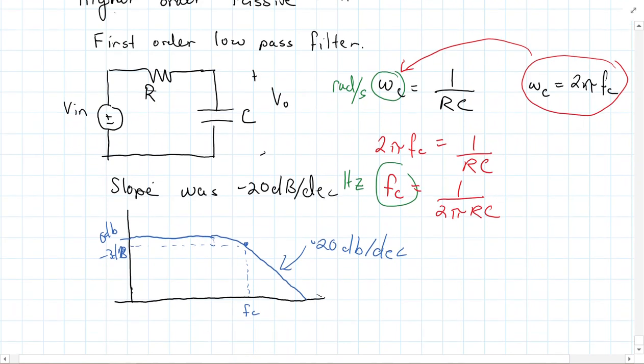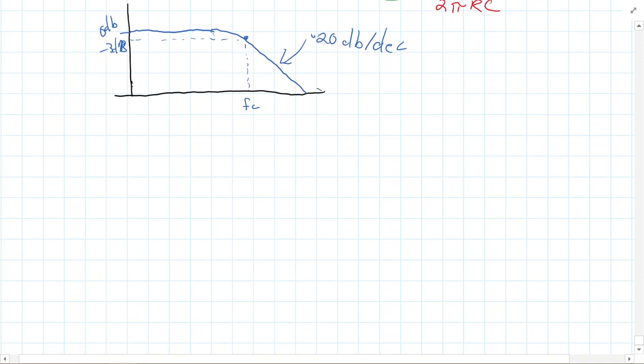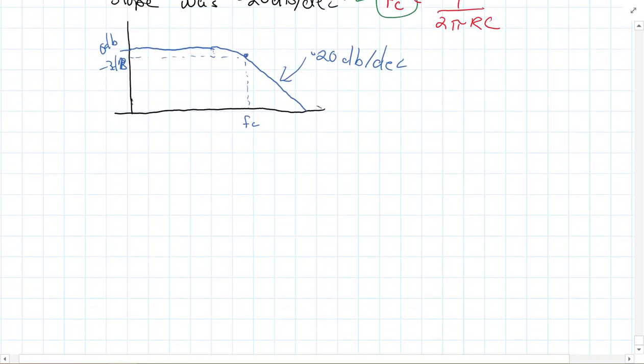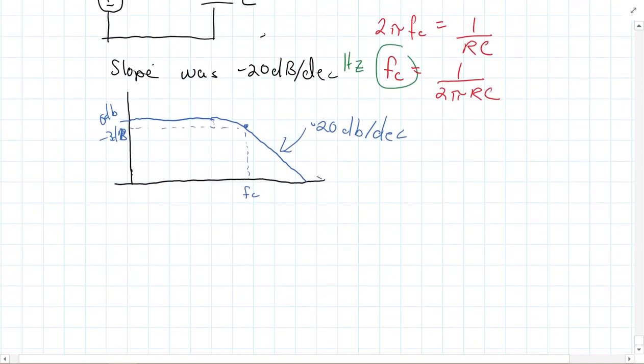That's what we're saying. Alright, so the idea here is we'd like to get a higher order filter, and we've seen some pictures before where I'm going to go through the same cutoff frequency but then have a steeper slope. So I can get closer to that ideal case, which I'll draw over top, being something like that, which we'll never obtain.